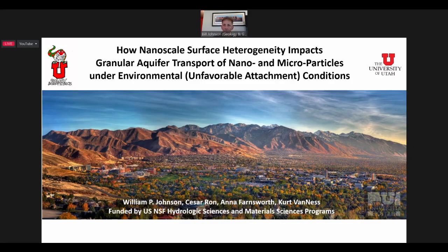that prediction because under environmental conditions, there is repulsion between these colloids and the grain surfaces. And it usually arises from there being like charged. And we call that condition unfavorable conditions for attachment. Because they, in the environment, tend to be both negatively charged, that creates a repulsion that makes attachment unfavorable, and it's very difficult to make predictions, as I'm going to show.